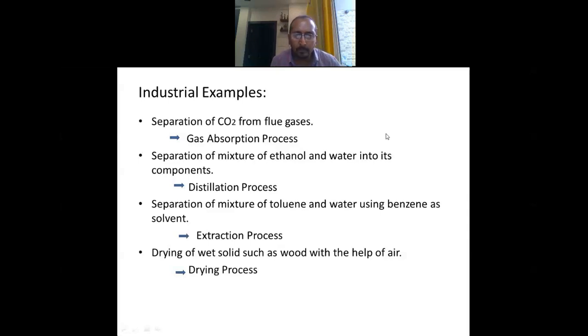So in all the processes, we have two phases and we are utilizing some property for separation. In gas absorption, we have two phases, gas and liquid, and we use the difference in solubility as the property for separation. In distillation, we use difference in volatility or difference in vapor pressure. In extraction, difference in solubilities. In drying, difference in solubilities. So we are utilizing some property for separation, and in all processes we have at least two phases. That is common in all processes.